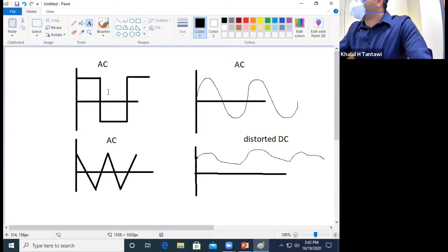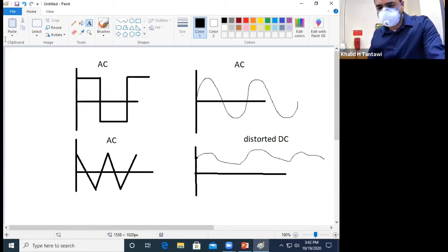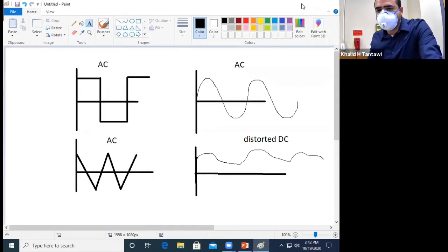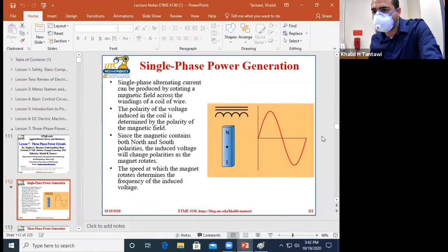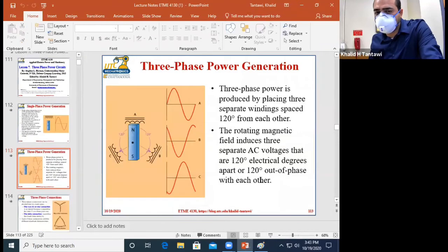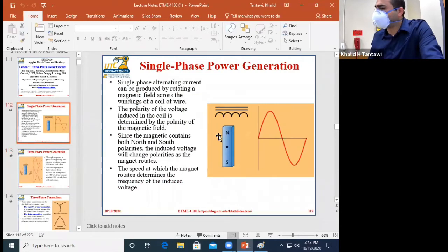So all of these are AC, but it's really the sinusoidal waveform that is going to be beneficial to you. The rest will eventually break down into sinusoids, and only one of the sinusoids will be used to generate torque for you. The rest will just be heating and vibrating. Is it clear? In other words, electromagnetism naturally only works on sinusoidal waveforms. If you try to push any other shape, you're just going to be wasting efficiency.